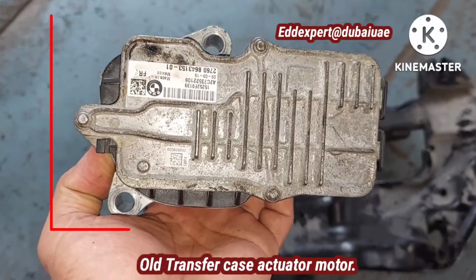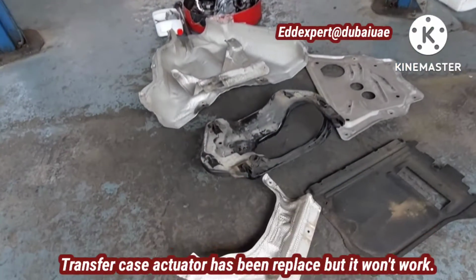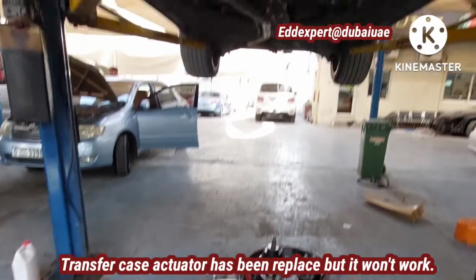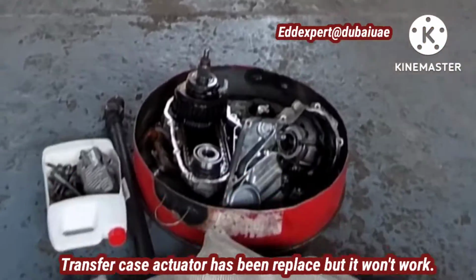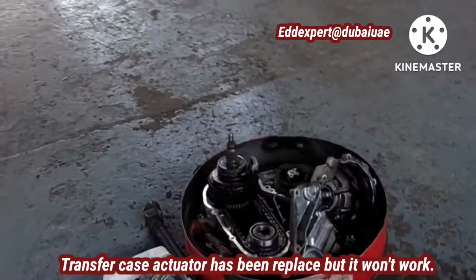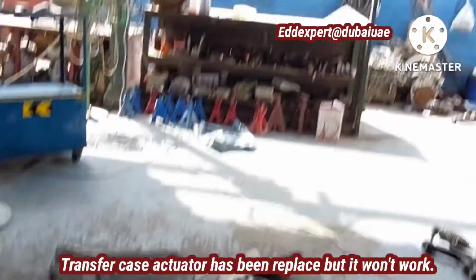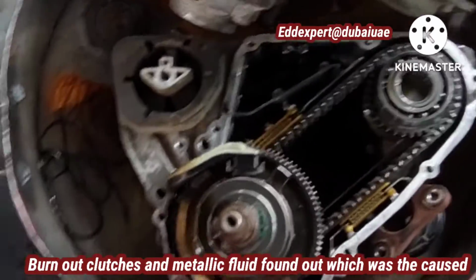This is the old transfer case, so I decided to dismantle all these things. We remove the underneath cover to give way for the removal of the transfer case. And I found out there are burnt clutches in the transfer case.